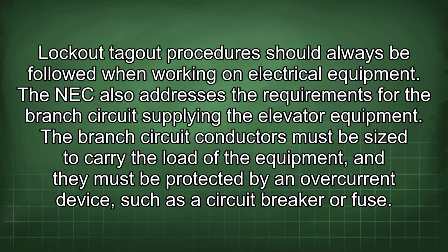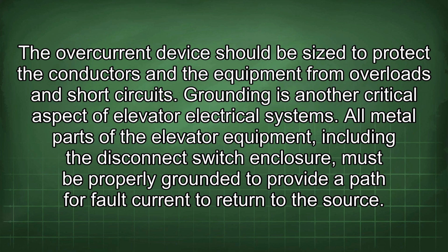The NEC also addresses the requirements for the branch circuit supplying the elevator equipment. The branch circuit conductors must be sized to carry the load of the equipment, and they must be protected by an overcurrent device such as a circuit breaker or fuse. The overcurrent device should be sized to protect the conductors and the equipment from overloads and short circuits.